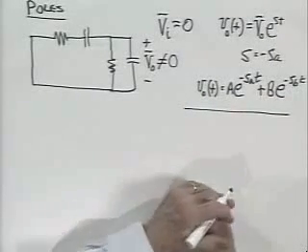So what we've seen at this point is that by focusing on the poles, the frequencies at which the denominator vanishes, we have in fact focused on the natural frequencies, the unforced natural frequencies of the network, the frequencies at which it will behave under unforced conditions, no source. And this comes from the transfer function of the network.